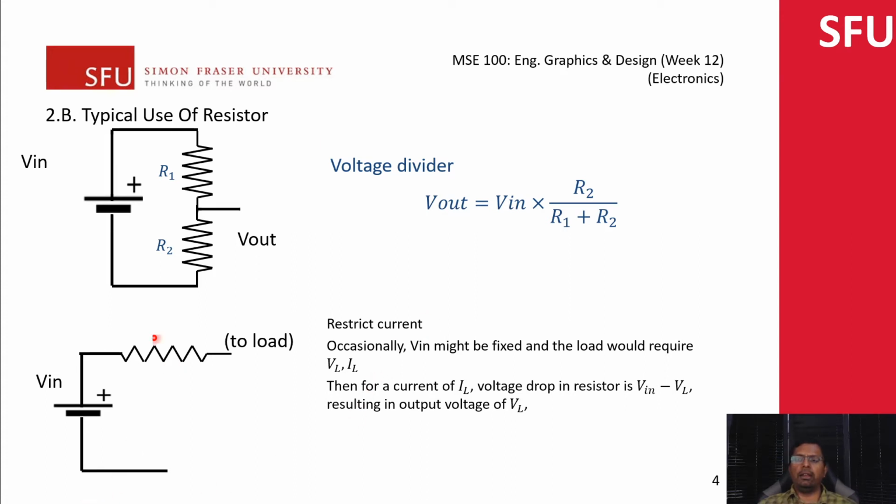You can also redraw the same schematic in a slightly different fashion. What you can do is call this point ground, as a zero reference. Then you can attach a ground to this point as well, and just get rid of this connection. Because both of these are connected to ground, it indicates that there is a connection between the two. It's similar to saying this goes all the way to ground, this is also ground, and you're assuming all of the grounds are connected to one another.